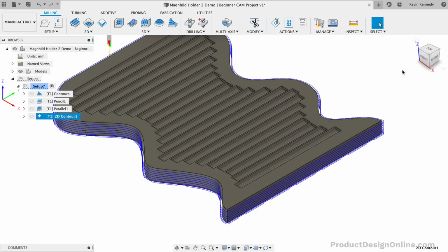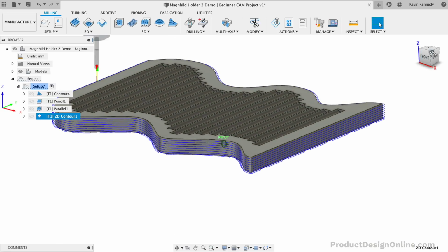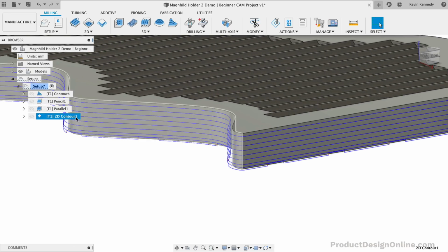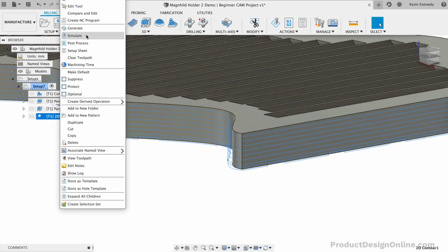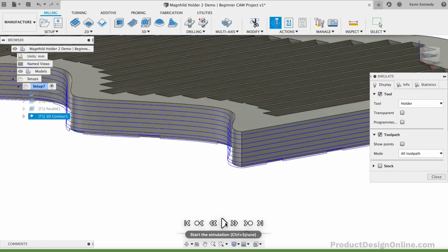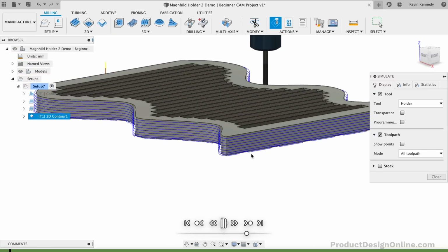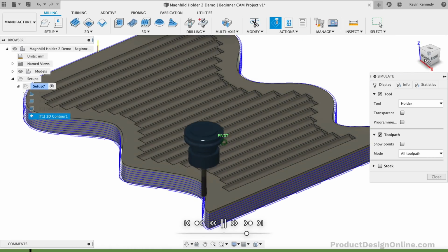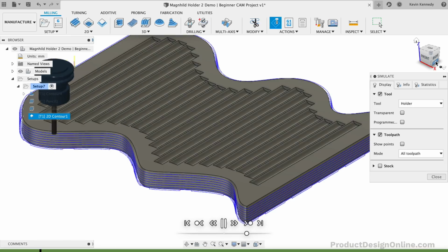You'll see there are several lines on the side that represent each pass needed as it steps down further into the wood. Once all of these toolpaths are set up, you'd be able to generate the code to run them on your CNC machine. It's important to note that any red errors in the simulate preview should be looked at before you run any real-life cuts.